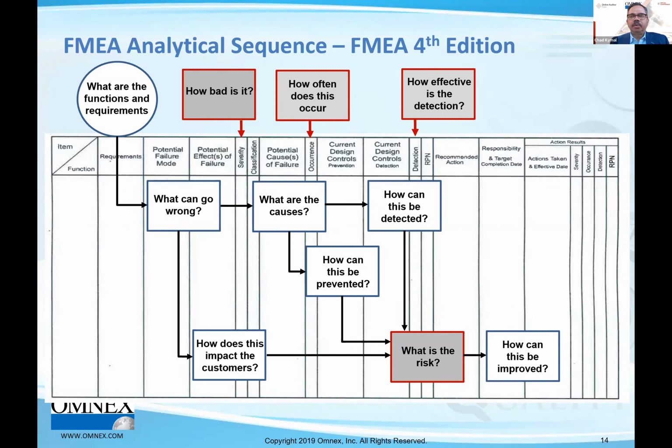If you don't see improvement, for me, I actually give that whole overall process even a major, because it's a complete failure, because the idea of the DFMEA and the PFMEA is improvement. Why do I say that? I call this the right side blank syndrome. This is the right side.